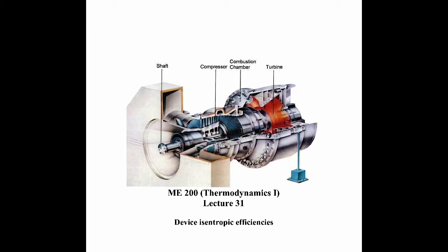If this was, for example, a steam turbine, or if this was to power some sort of piece of machinery, what you'd want to do is have a lot of energy coming out of here to rotate that shaft, so you get a lot of shaft power. For an aircraft engine, you would just pull out enough energy from the turbine to keep the hydraulics, the electronics and such running, but most of that energy you'd want to keep in the flow and then have it leave the back end at a very high speed, a lot of kinetic energy, so that you can provide a lot of thrust for the aircraft.